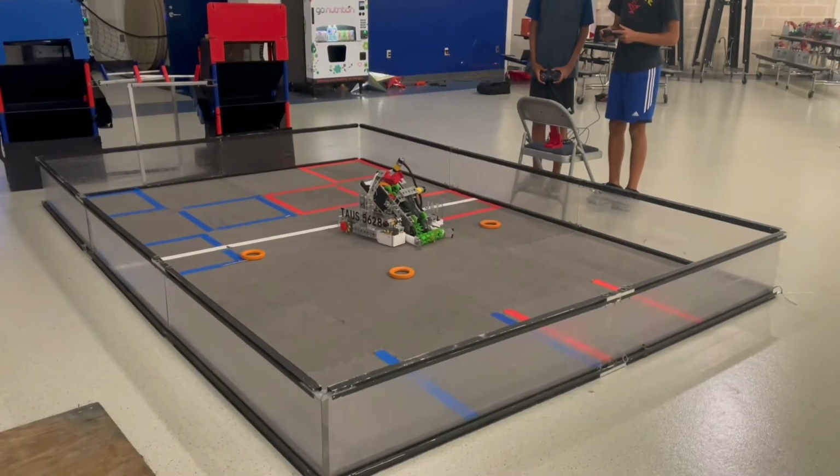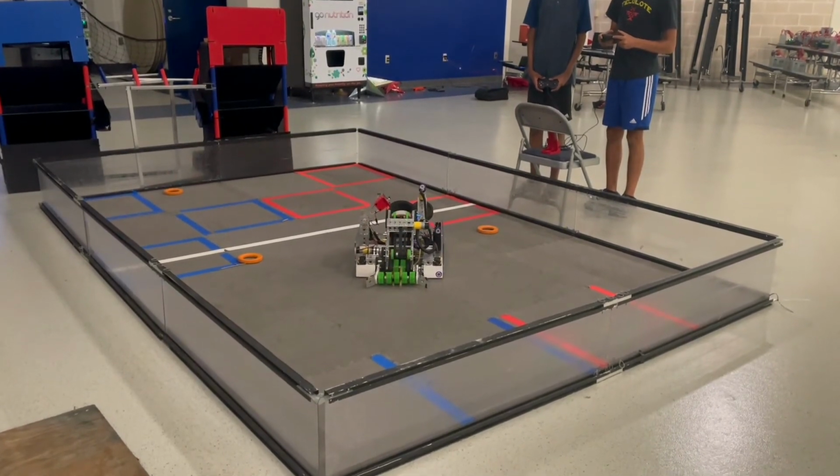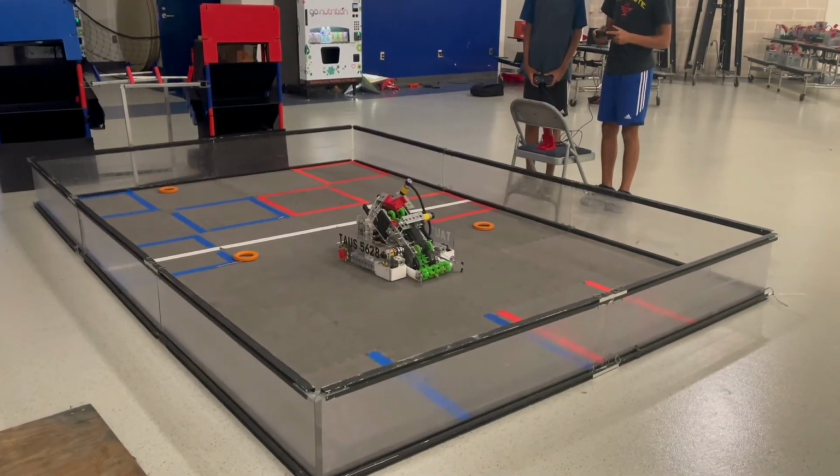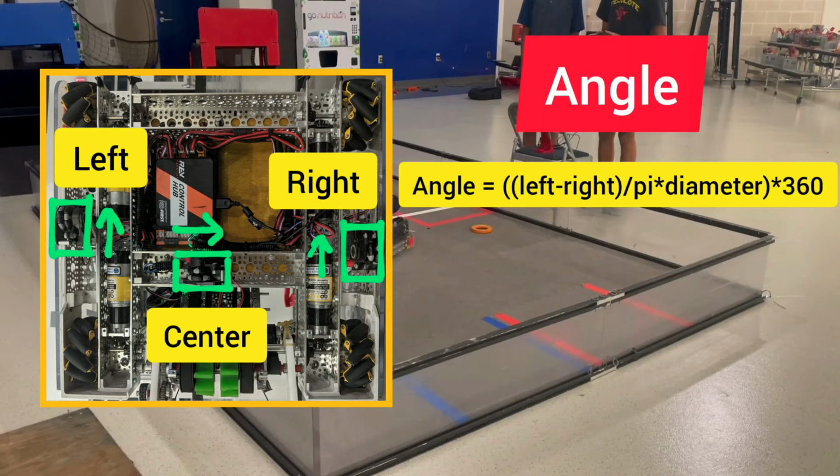To maximize the amount of rings we could score, we took on the ambitious task of shooting from anywhere on the field. This requires two things: knowing our position on the field and using it to calculate the angle and RPM of shooting. To do this, we used dead wheels, free spinning wheels that use encoders to record distance. We developed a set of formulas that allow us to find our position using these three wheels. We used the difference between the two vertical wheels to find angle.